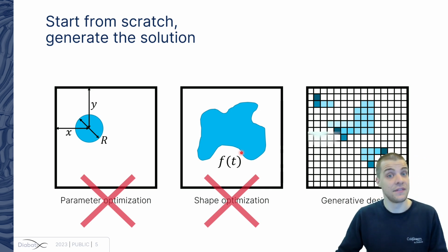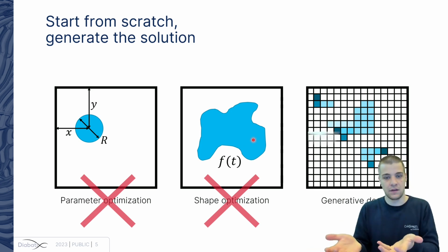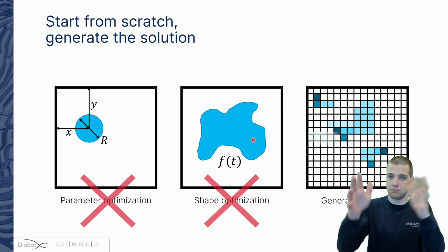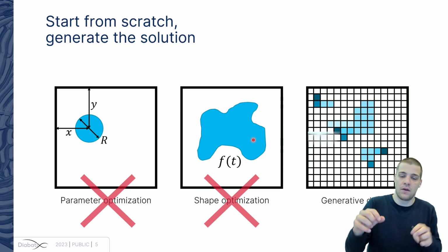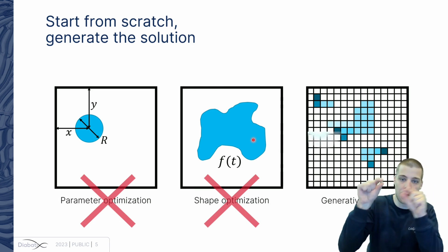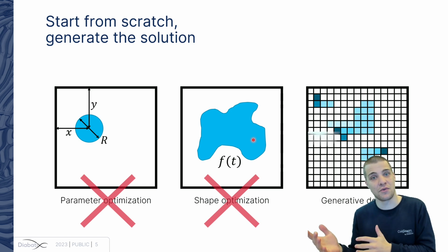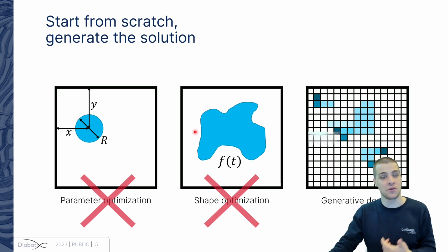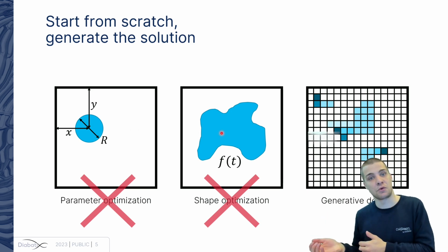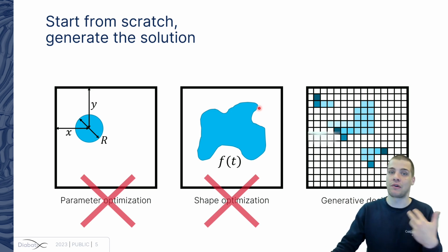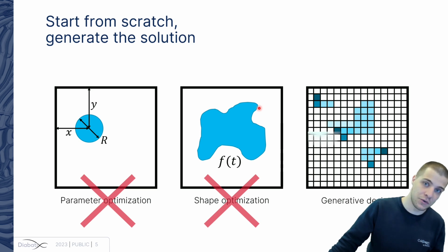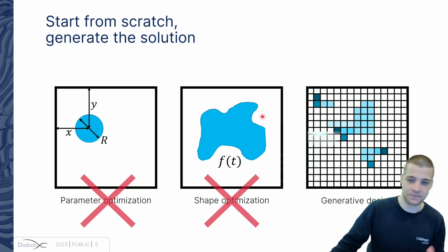Then there is something called shape optimization. With shape optimization, you initialize a given design, and then the boundaries, so the shape of your initial design, are further optimized. The potential solution is much more complex than what you can get from parametric optimization, so inherently it's more optimal, but the eventual solution is very much dependent on your initial condition, so it's not fully optimal.